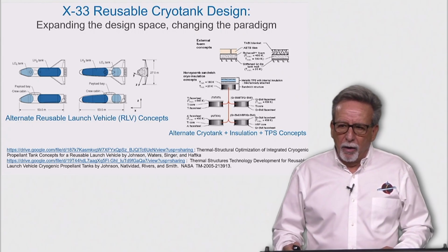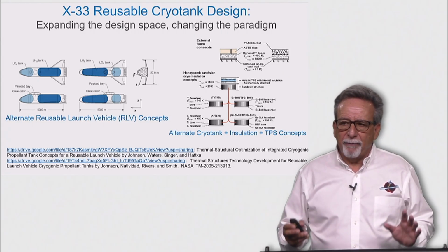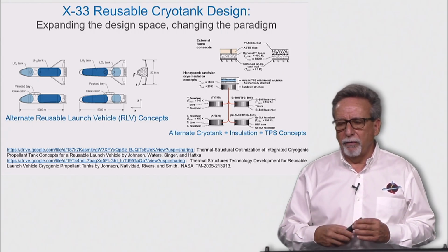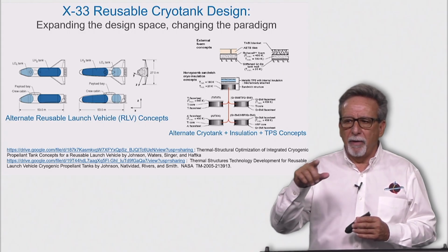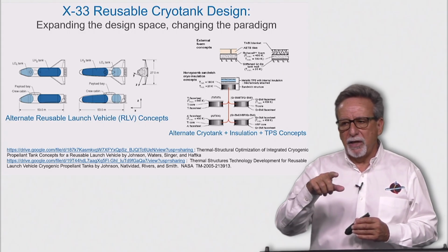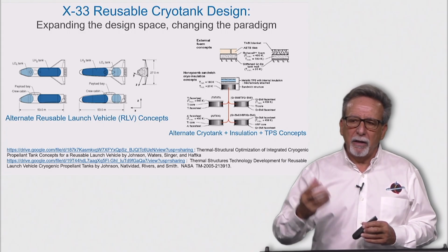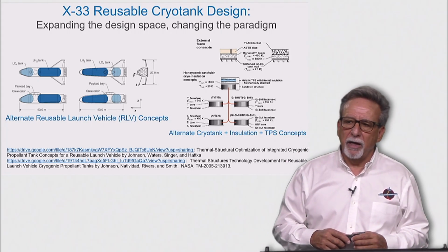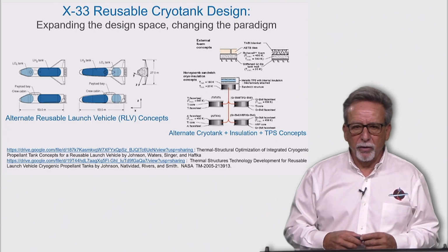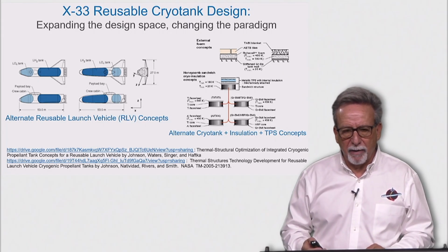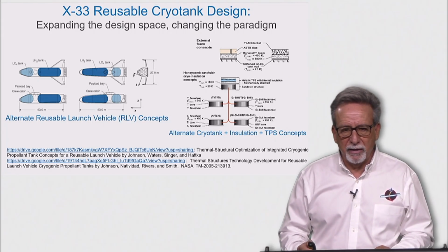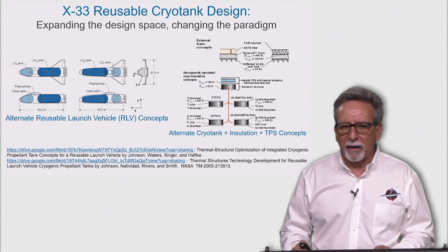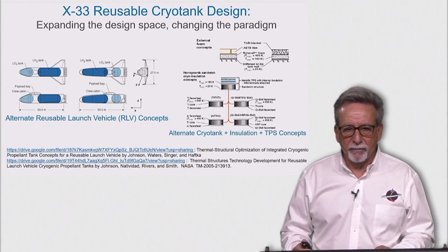So we're including in this optimization, remember, as we're going through this analysis, experiment, and optimization loop, we're looking at many different ideas for minimizing the mass of this tank and TPS combination. We're looking at metallic tanks versus composite, aluminum versus titanium, and external ceramic bonded TPS versus metallic mechanically attached TPS.